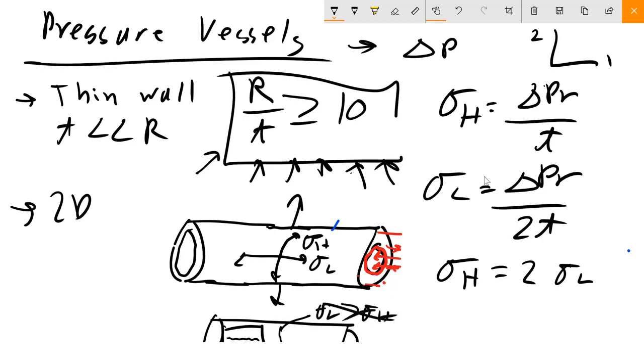That's not the case at all. Again, in this scenario, if there's no defects, there's no stress concentrator. So you should expect to see a crack like this. And actually, if you go and look online, you'll see, again, for cylindrical pressure vessels, that is your common kind of fracture pattern there. So that is basically these pressure vessels in a nutshell.